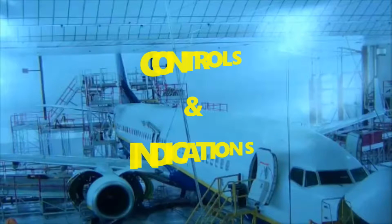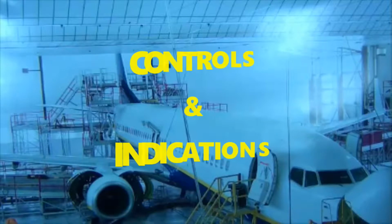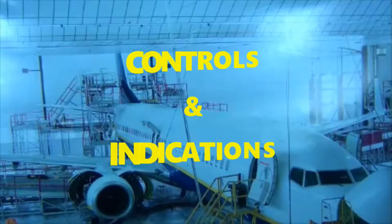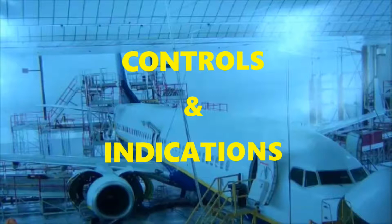If it's going to need to be opened, or it's desired for it to be open, then you're going to have that green horizontal line. So you have that crossfeed valve indication circle with the green horizontal line. You also have an amber colored either horizontal or vertical line or a slanted line. So if the amber color shows up, look at the position of the line on the indication.